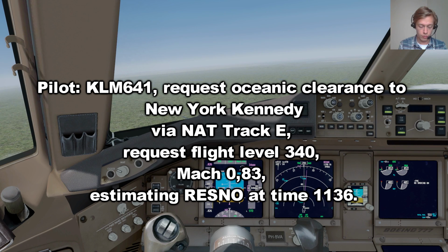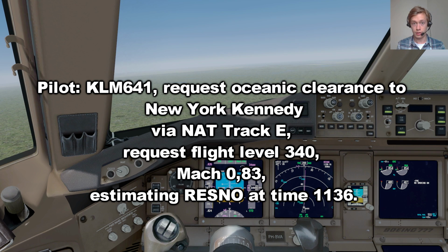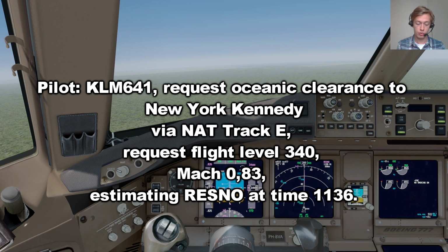KLM 641, request Oceanic clearance to New York Kennedy via NAT Track Echo. Request flight level 340, Mach decimal 83, estimating Resno at 1136. There we go. So that's the basic Oceanic clearance request. We fly via NAT Track Echo, we request flight level 340 and Mach decimal 83, and we estimate Resno at 1136 Zulu.